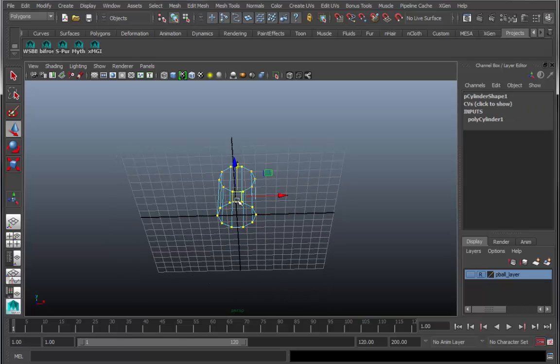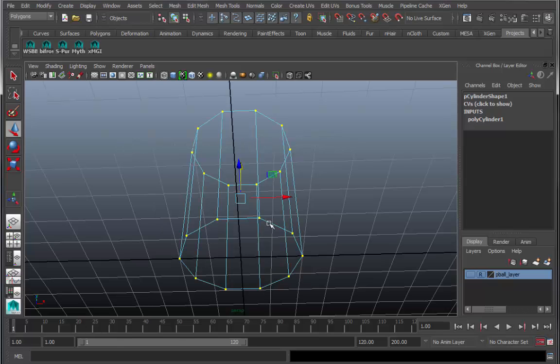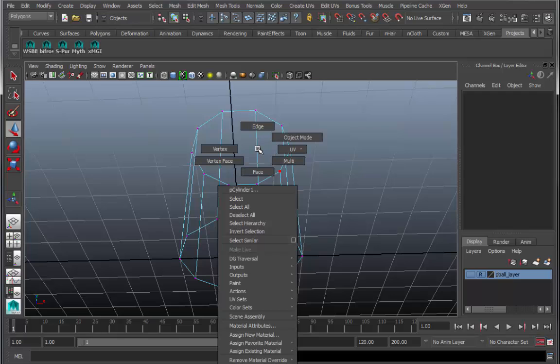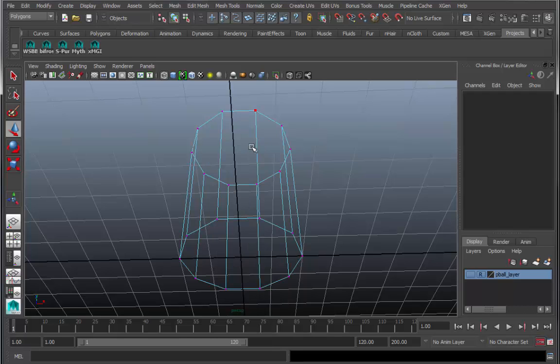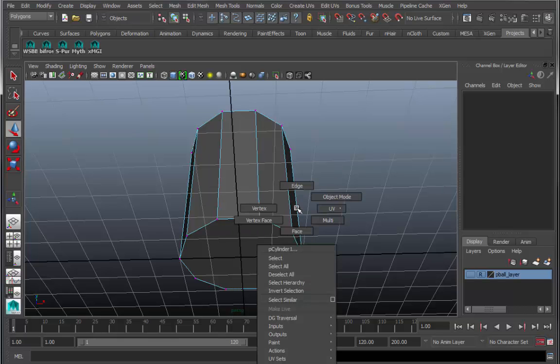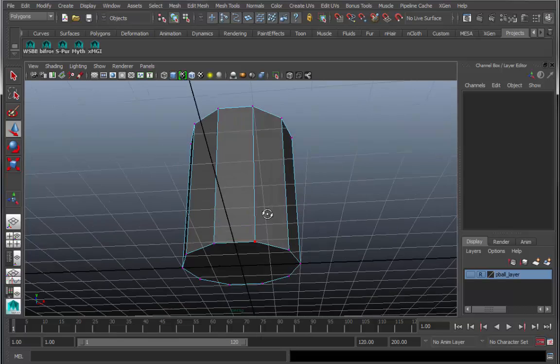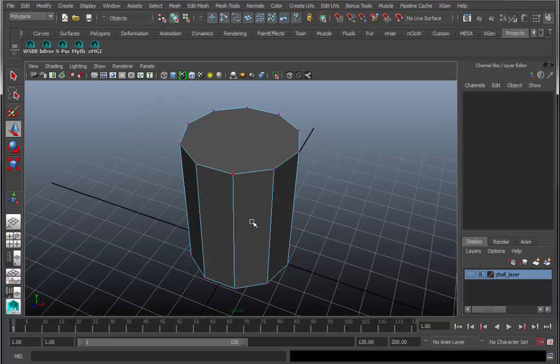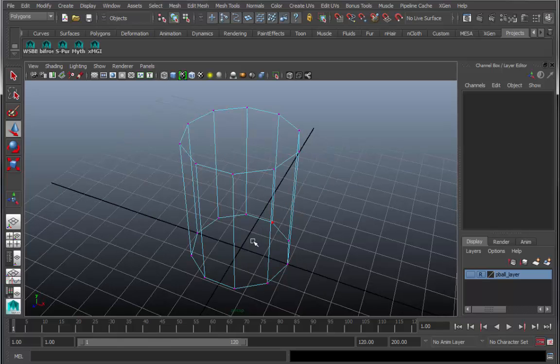Could we have done it with the face? Yes, we could have. This is an interesting sort of eccentricity of Maya. When it's in wireframe and you try to evoke the drop-down menu, it doesn't see it as a selected object until you're right on the wireframe. Then it gives you your modeling options. In shaded mode, you're basically on that shaded surface at all times. So this is why you're going to see the drop-down menu when you're in shaded mode, and yet the very same space when you're in wireframe does not give it to you.